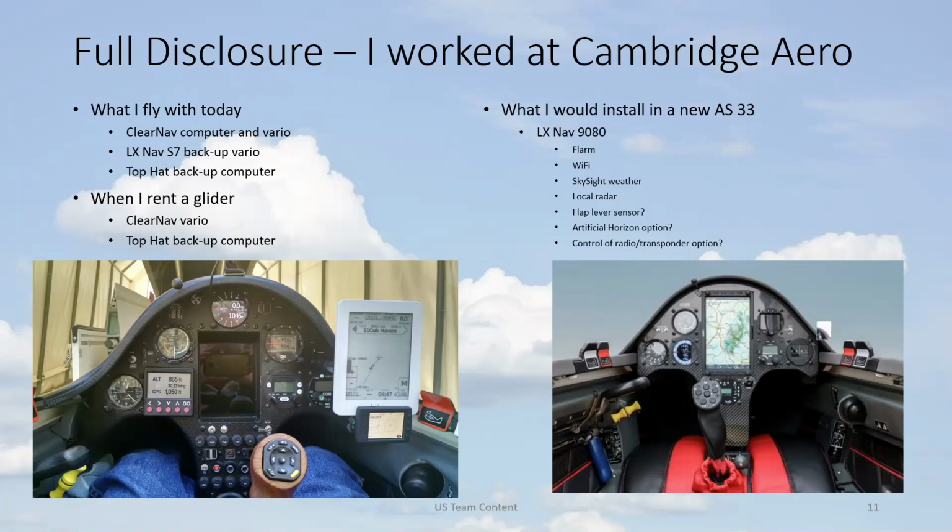Of course, there's also the option to use Schottky diodes, right? And have all the batteries connected. That way the Schottkys prevent the batteries from discharging each other. The price that you pay is about half a volt of drop if you use the Schottkys. Yeah, I tried those on my solar cells, and they didn't work very well anyway. The key thing with that half a volt drop is after 3 or 4 hours, you're going to get your radio complaining about low voltage.